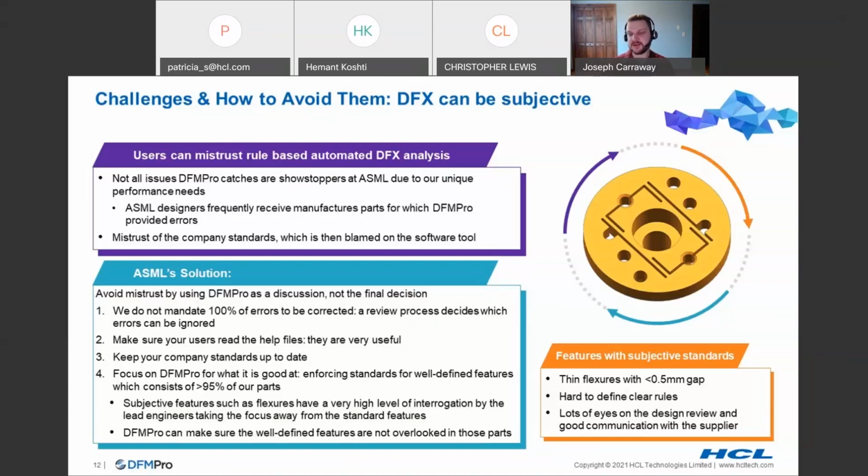The software was actually assuming that you were machining the part from the opposite side of what the designer thought. This is because there was an overhang in the part. They spent a couple days looking at this error, and then they finally understood when I told them to read the message. The other thing is read the help files.